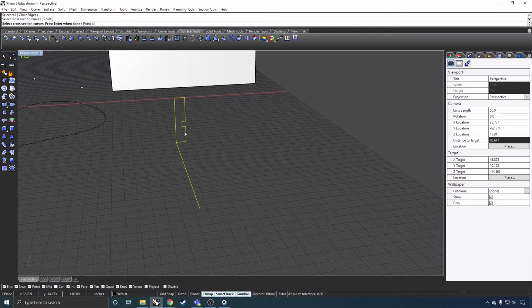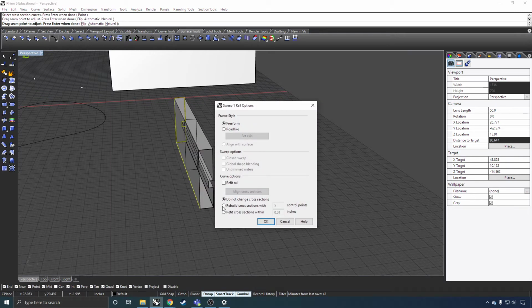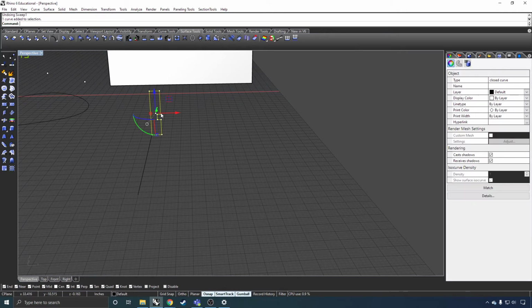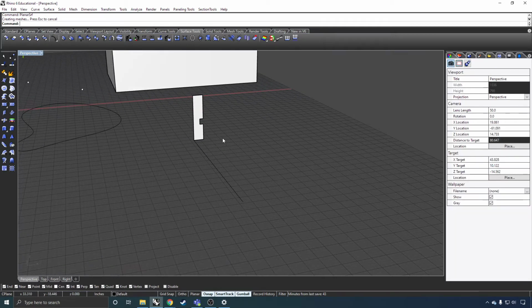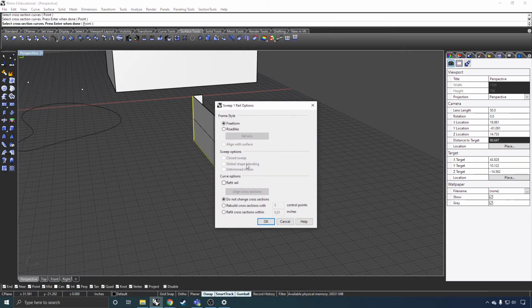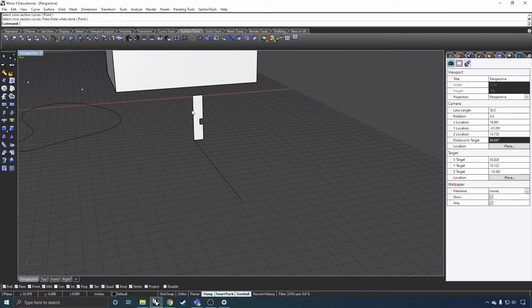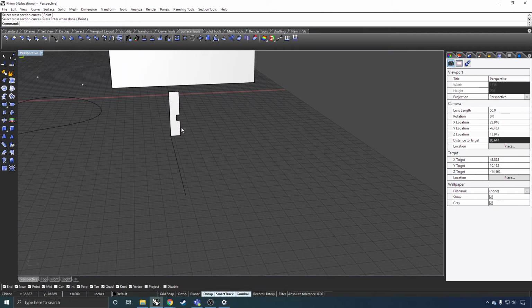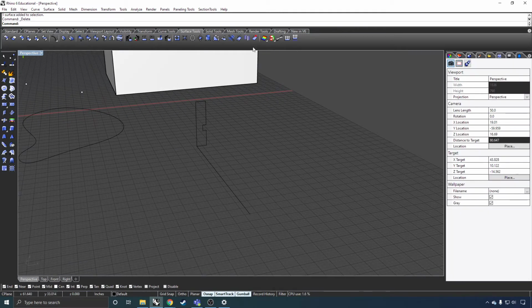If we do this again, and if we make this a surface instead of a polyline, and then sweep it with the rail and the surface edge. Oop, it's only pulled one edge. There's a way to do it where that closes automatically. Oftentimes I just use a command called cap, but it's not that important. It's useful for generating some geometry, but this is really detail-y.